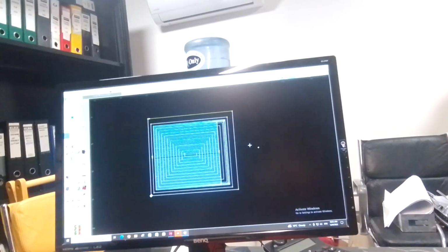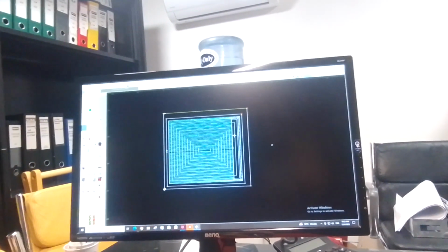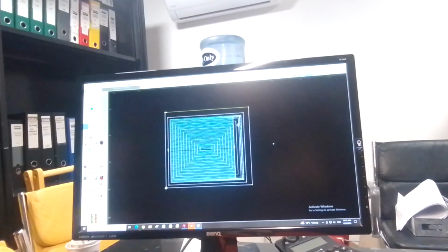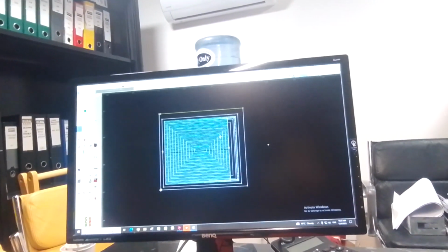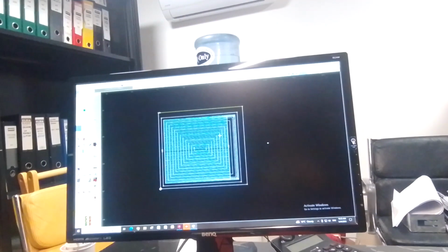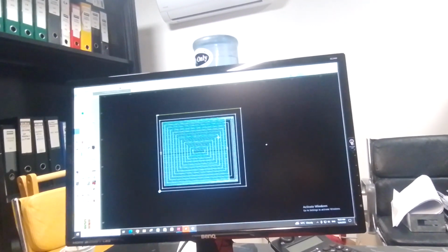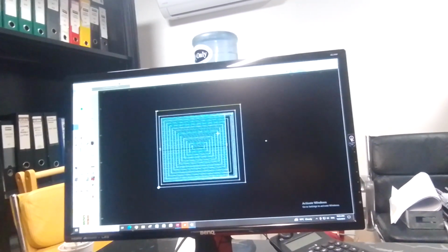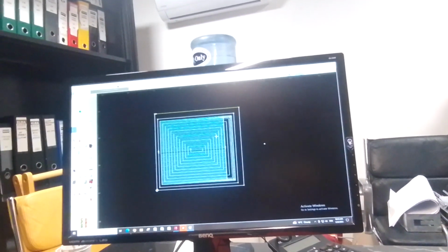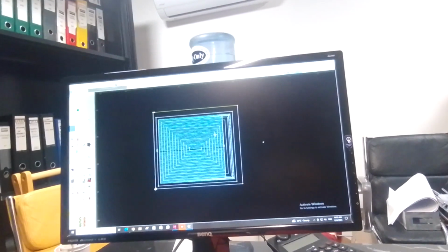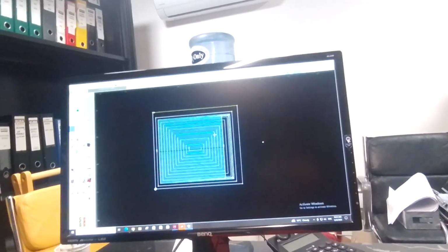Okay. After that, you can add with the same tool or with another tool. Maybe better. In this machine, you don't have the tool change automatically. So it's not worth it. Here it would be better if we get the inclination done, and then we can put it on the water jet, and the water jet does the hole. Or else we can work vice versa. We can do the hole, and then get the work done.